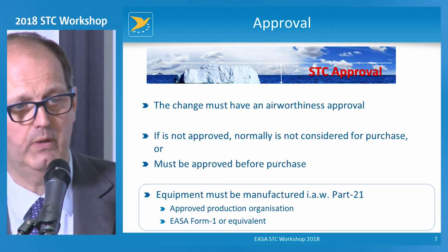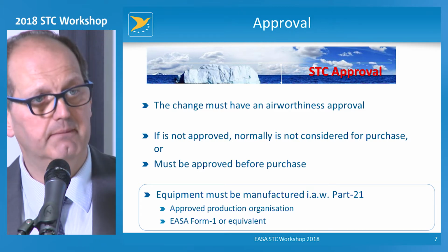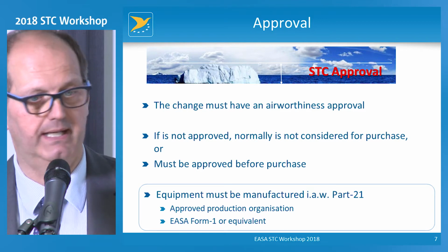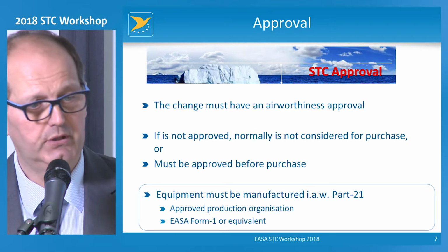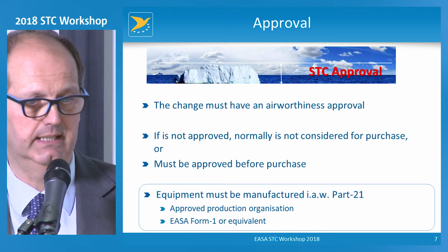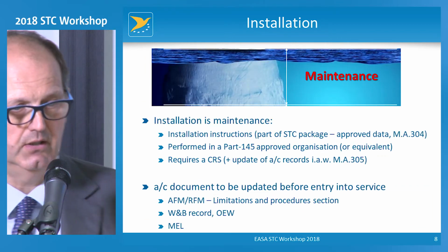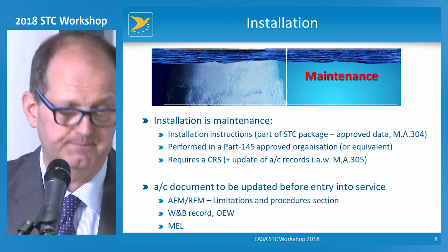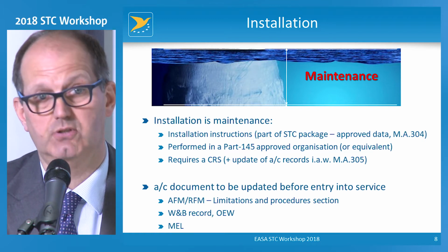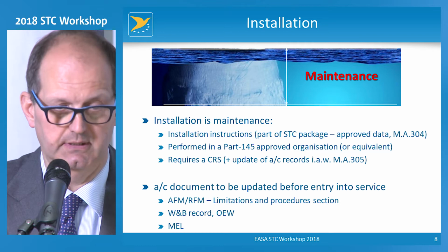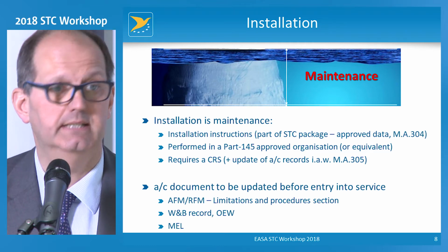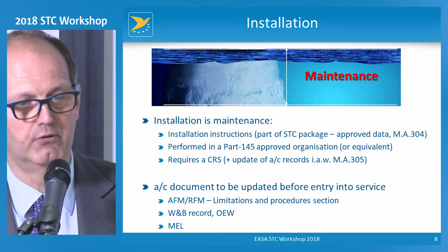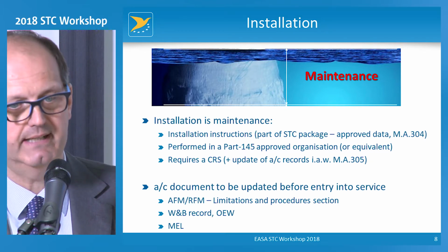So now we have our head-up display, which is approved and covered by an STC. We have a beautiful EASA piece of paper, and we need to install it on our aircraft. First thing to do is to go to a maintenance organization and have it installed. There must be installation instruction, and normally they are part of the approval package of the STC.